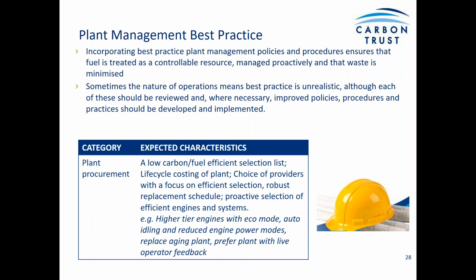And certainly from the outset of a project, you're wanting to look at the process of the actual plant procurement, looking to hone in on specifying the higher tier engines, which would have the incorporated eco mode with the auto idling and all of the reduced power modes.